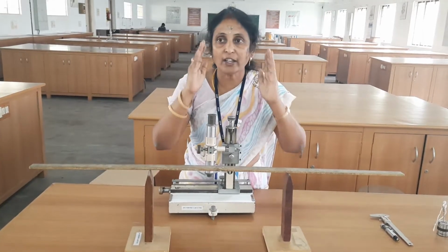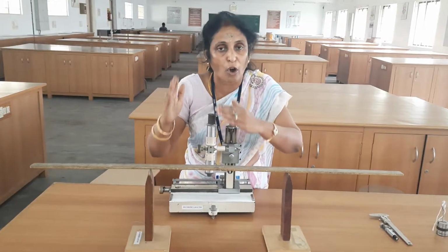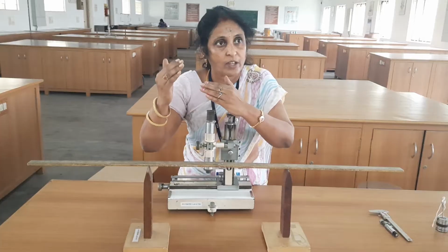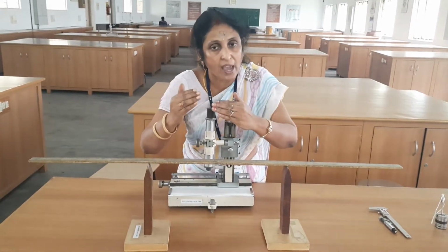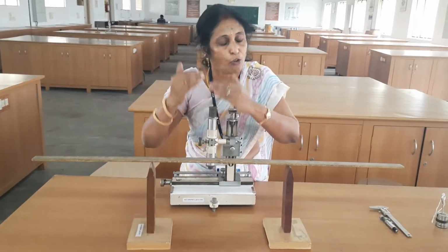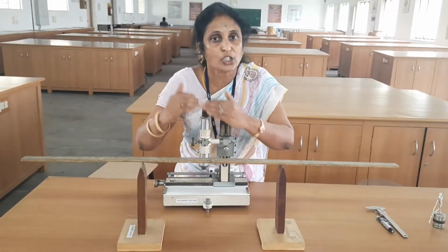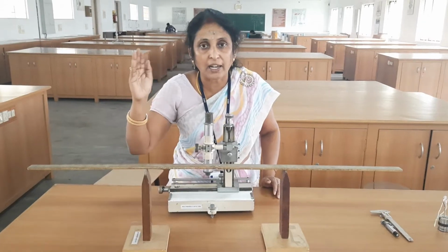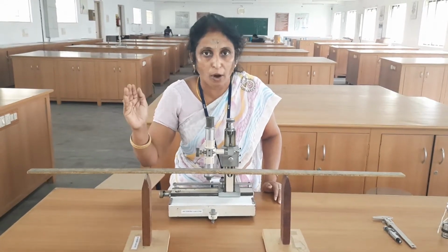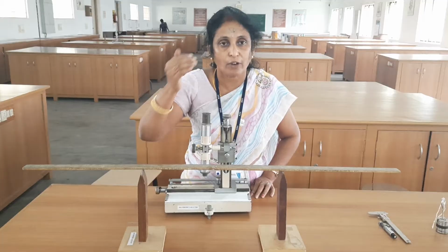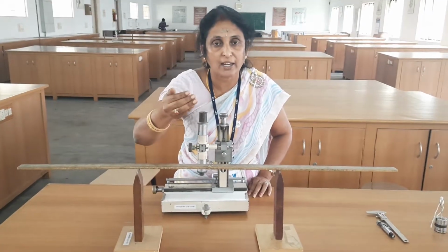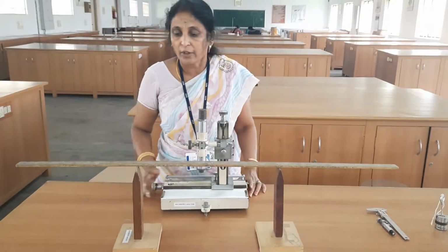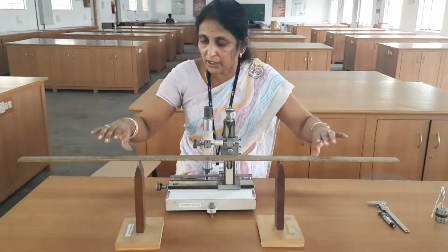So when you find the Young's modulus, capital Y is equal to longitudinal stress by longitudinal strain, then you will get F by A, force per unit area, divided by change in length by original length. So you will get Y = F L divided by A into small l. So the unit for Young's modulus of the material is the same as that of the stress, that is Newton per meter square. Okay, now we will go for the method of this experiment.